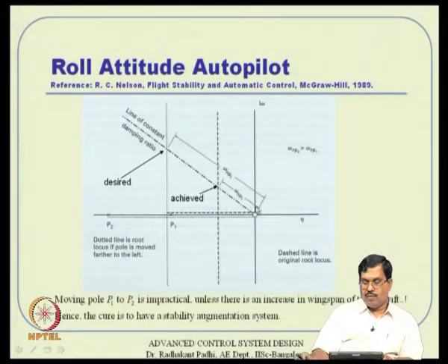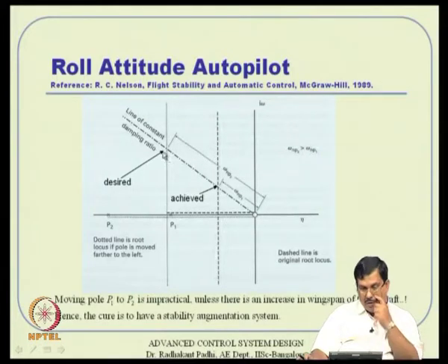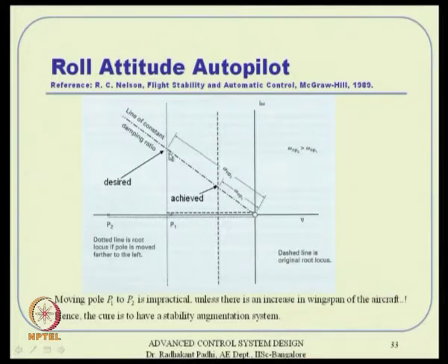Observe this condition now. Let us say we somehow extend this line. Remember, the magnitude of this length gives us omega n. That means, if I keep on moving along that direction, obviously my zeta remains constant because the angle remains constant, and at some point I will get the desired omega n. So, this point happens to be that point.